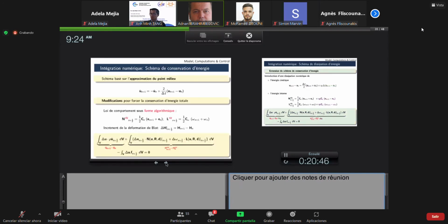fragile and stops. So basically, the reason how we build these time integration schemes, you're probably familiar with the Newmark scheme, which is kind of an average acceleration. Here we take something which is called a midpoint scheme. We actually introduce the difference between 2 displacements as, let's say, the average of the velocity in the middle. And then we switch in computing the strains, not to this type of approximation, but to the approximation. That means you don't take an axial force or whatever, the moment, to be computed at n plus 1/2. Remember, these are nonlinear measures, but we take the value at n and the value at n plus 1 and divide by 2.